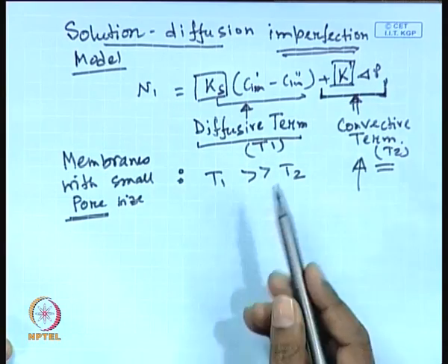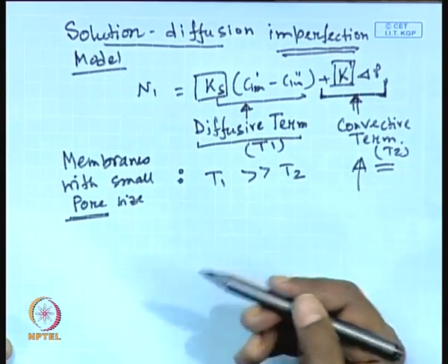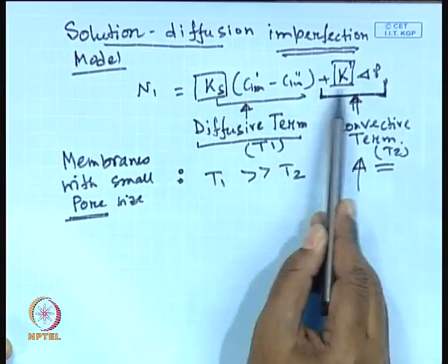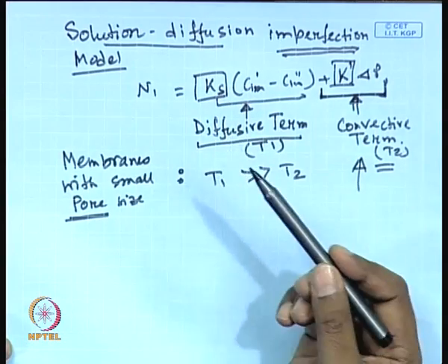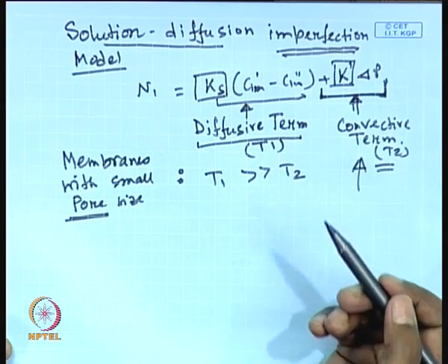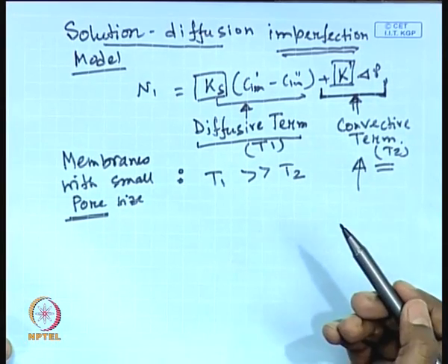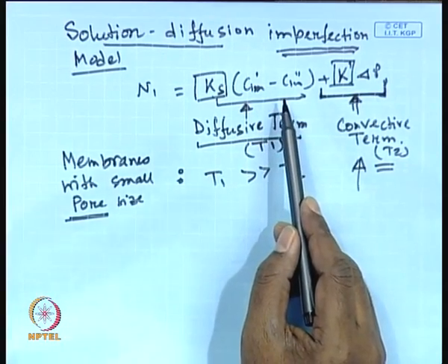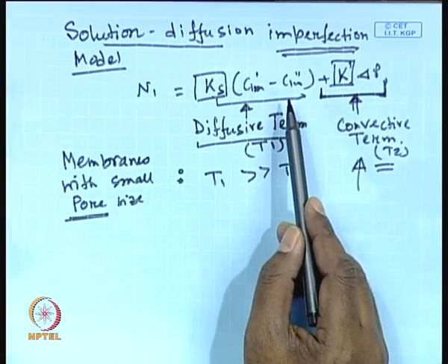So, what you are going to do is some calculations using assumed values of these parameters, get the value of the permeate concentration and the permeate flux, and compare these values with the experimentally measured values of the permeate concentration and permeate flux, and see the error involved. If the error is large, then you have another guess set of these parameters. Likewise, you can keep on iterating and doing an optimization study.